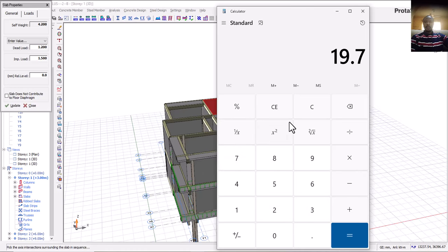This 19.7 is our load, both the panel and the water that is going to be sitting on this particular slab or roof. Is that okay? Now somebody said that we're supposed to divide this value by the factor, our factored value, which if you see it as a dead load, we now divide by 1.4. Then whatever we get becomes the value we put here. That is not correct.